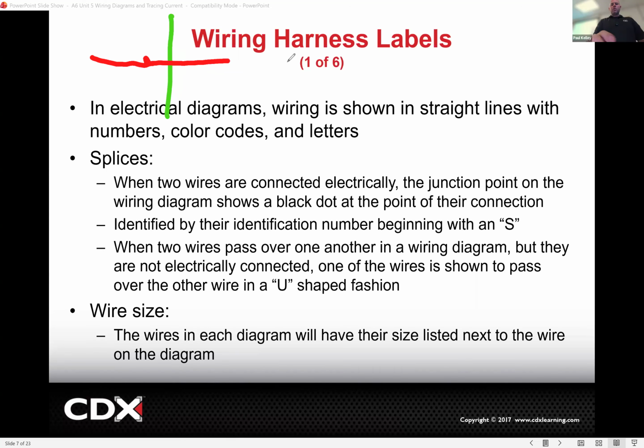This would be confusing to me because it's like, is it connected? Is it not connected? I'd say generally this is going to be a no. But if there were two different colors and it came together with an intentional something, then those are definitely connected. The good news is it makes more sense if you have a green wire, let's say it's ground, and they bring another wire over, they're probably going to have that wire be the same color because they're both ground, right? So it'd be a little abnormal to have different wire colors come together and be spliced, but it's not unheard of.